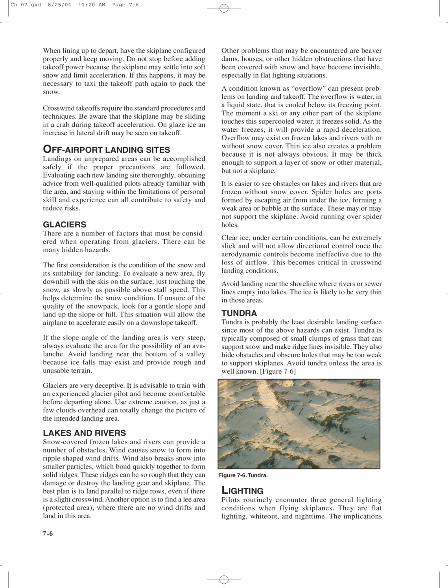A condition known as overflow can present problems on landing and takeoff. The overflow is water, in a liquid state, that is cooled below its freezing point. The moment a ski or any other part of the skiplane touches this supercooled water, it freezes solid. As the water freezes, it will provide a rapid deceleration. Overflow may exist on frozen lakes and rivers with or without snow cover.